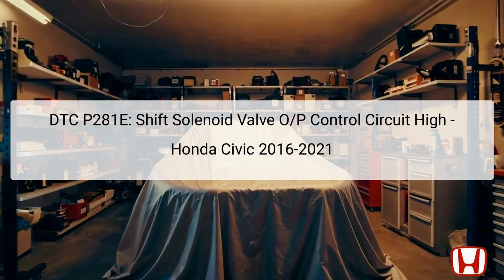DTC P281E indicates a malfunction in the Shift Solenoid Valve OP control circuit, specifically related to the pressure control solenoid H. This diagnostic trouble code, DTC, is associated with the Honda Civic models from 2016 to 2021. The fault arises when the transmission control module, TCM, attempts to manage the electrical signals to the shift solenoid valve, but detects discrepancies. When there's an issue, it results in incorrect pressure control for the transmission fluid, which can lead to performance issues in the vehicle's operation.